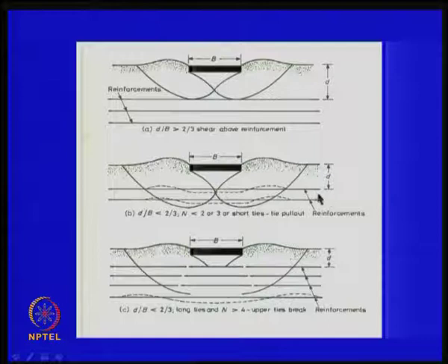If the length is not adequate, it may not really develop frictional resistance completely, and even if the friction is developed, it should be able to sustain that friction by pull-out resistance. So, that is the reason I said the factor of safety, there is always a relationship between the pull-out resistance and also the tensile force developed. Okay. So, if the short tie occurs, then there is a slip. So, this is what we just tried to show in the form of a slip. So, short ties lead to tie pull-out of the reinforcement, tie pull-out we call it.